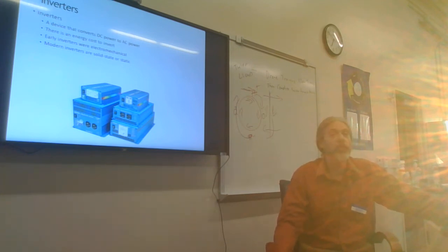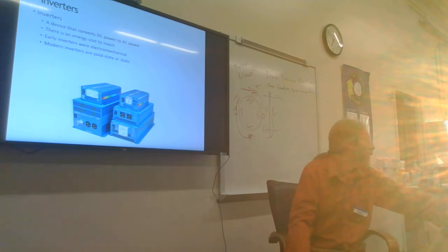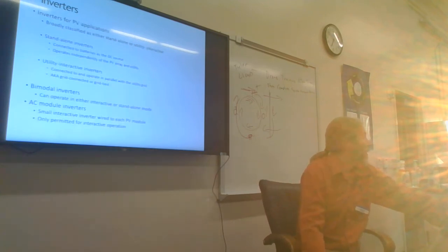I do believe that the inverter is one of the weakest links in the PV chain, especially for grid-tied systems. If you're going to have a failure point, the inverter is the most likely chance for a failure point. I do recommend buying extended warranties on the inverters. Normally, it's only about a 10% cost addition to add 5 years additional. So you want a 10-year warranty, you got an existing 10-year warranty, you want a 15-year, add 10%. You want a 20-year, add 10% more to that. Inverters are getting cheaper. That is for sure.